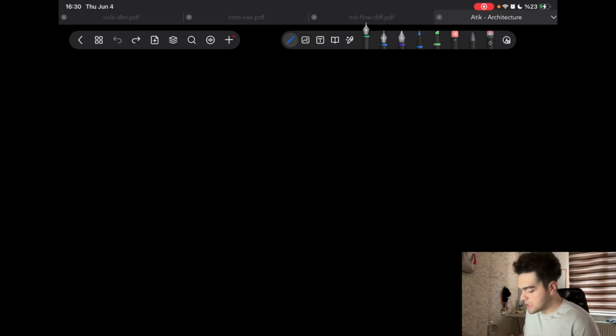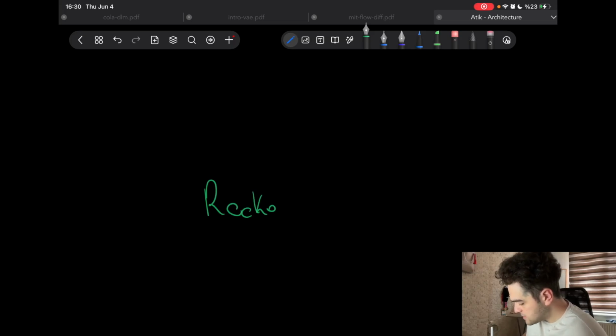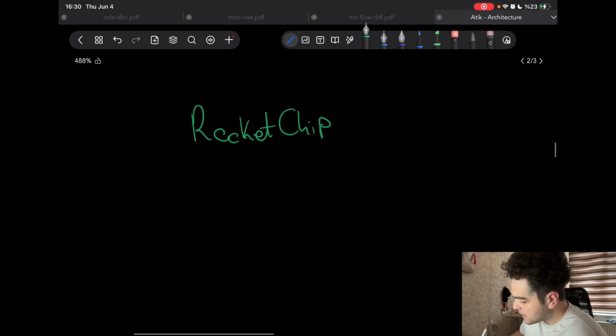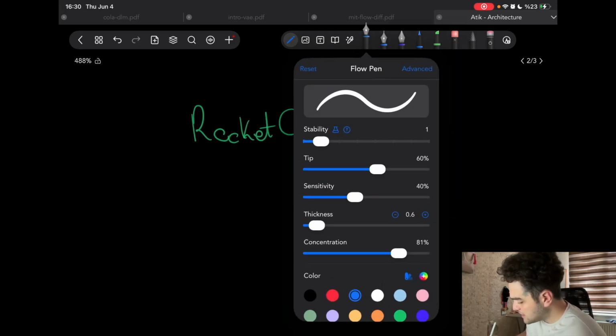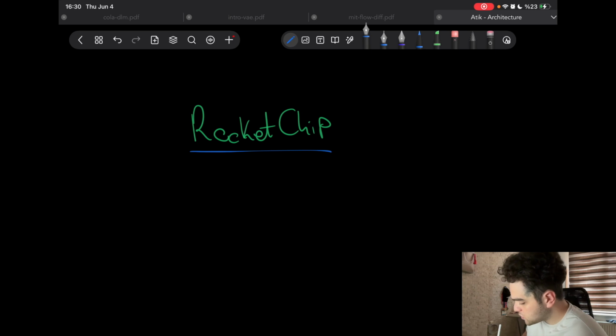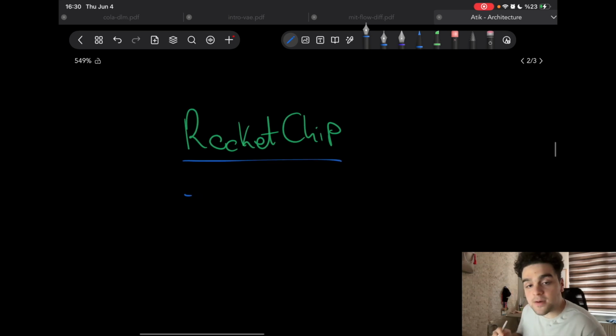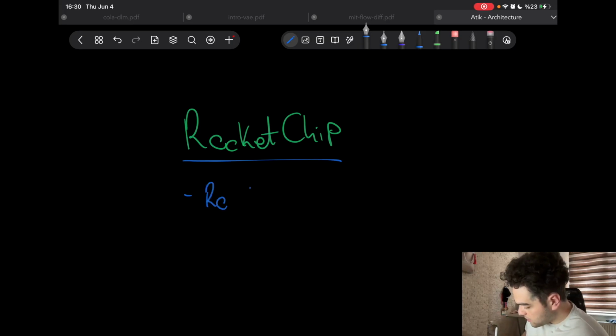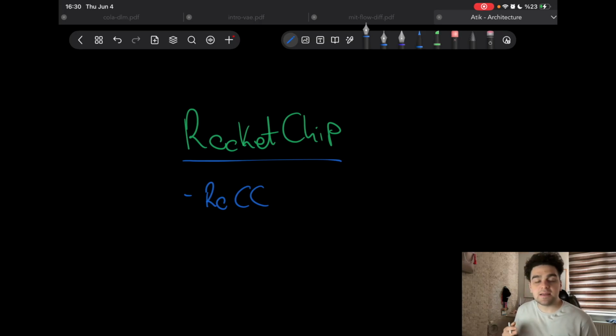I'm going to use a microarchitecture called Rocket Chip. This Rocket Chip is a microarchitecture built by UC Berkeley, and one of its main advantages is that it allows you to add an accelerator to it. So it reserves a place called Rocket Custom Coprocessor, or briefly RoCC, that is a tightly coupled accelerator. We will build that tightly coupled accelerator and attach it to this microarchitecture.